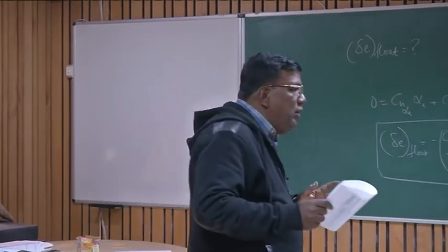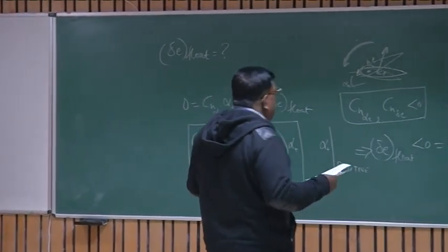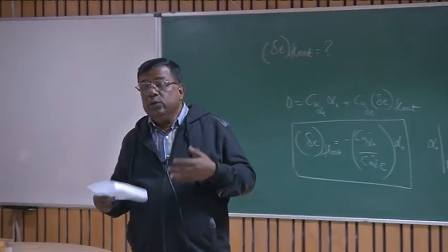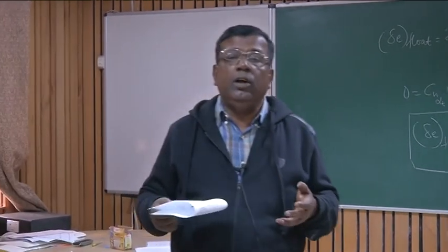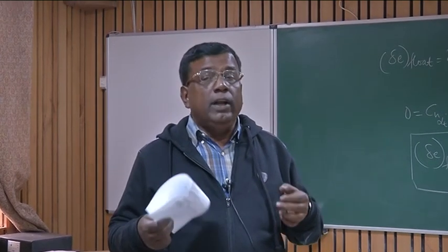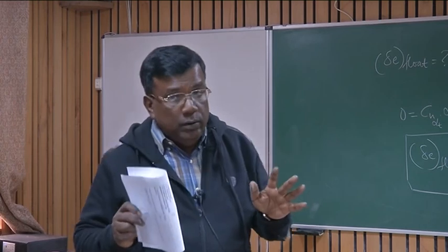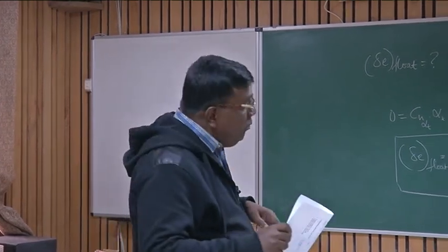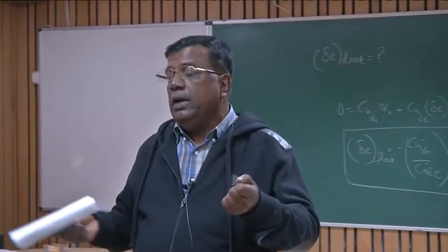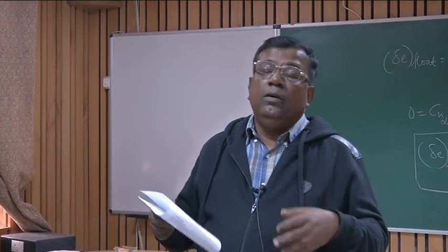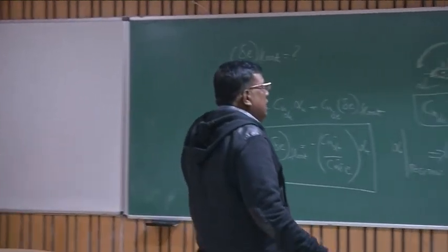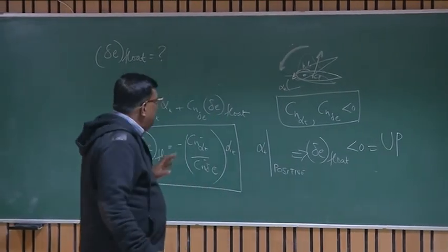But in a nutshell, you understand that since it is floating up, we must know how much it will float, and we should use this concept to define a mathematical model which will relate stick force and CL trim for a reversible control, right? That is the catchword, reversible control. Because for irreversible control, there are boosters in between, so the relationship between pilot force and actual deflection is overridden by the actuators and the boosters. So you cannot give a direct feel. Of course, artificially they are simulated, but that is not our purpose. So this is delta E float. Thank you very much.